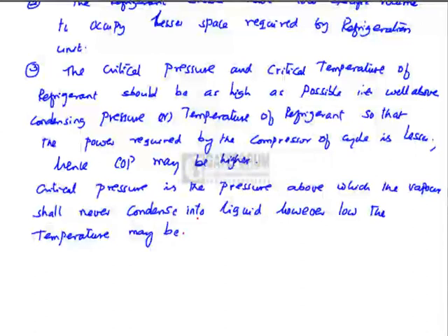If the pressure of the refrigerant is above its critical pressure, whatever the cooling you provide for the refrigerant vapor, it would never condense into the liquid.